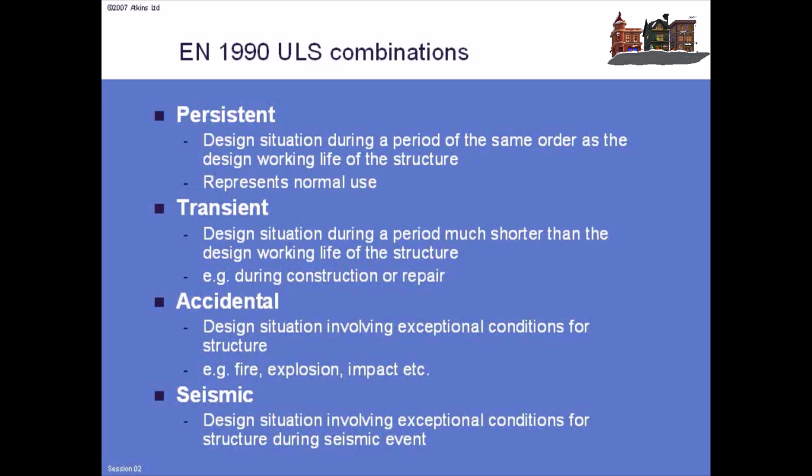So the persistent load combination, for example, represents normal day-to-day usage of the structure. And that's really the combination you'll typically be doing the design in, and it's likely to be the governing combination for the design. We have something called a transient combination, and this is really picking up on things like construction, where if you have loadings with a shorter term duration, you might want to consider them in the transient combination so that you can reduce their impact from the full characteristic values. But equally, you might just be conservative and take it in the persistent combination.